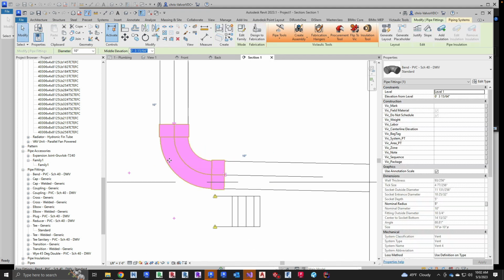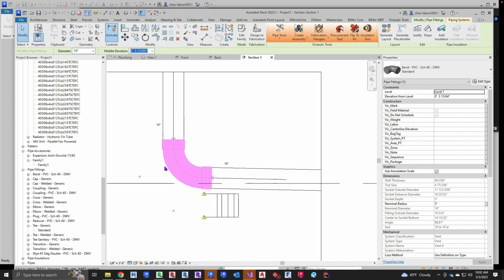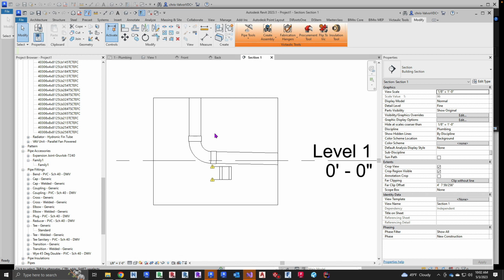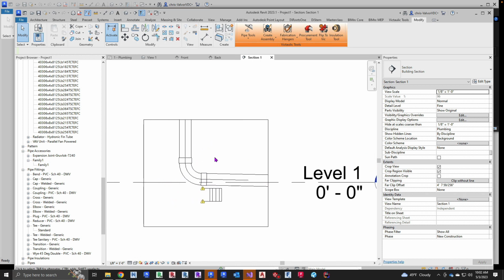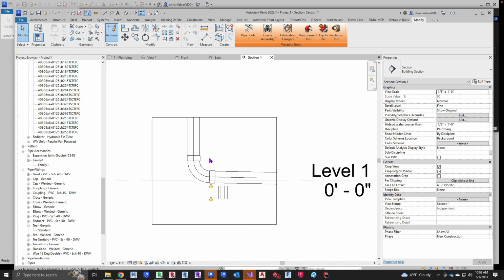And you've probably experienced that at some point where it'll say something can't be built or whatever. Right. And it just loses that. So when you're building your families, you always have to remember if it's going to move, you have to have at least a 32nd of an inch sliver there to do it. And you can usually get away with it. So that's another thing about families that are something that's here or there. But for the most part, most manufactured families are crap. Some are good, some are bad.